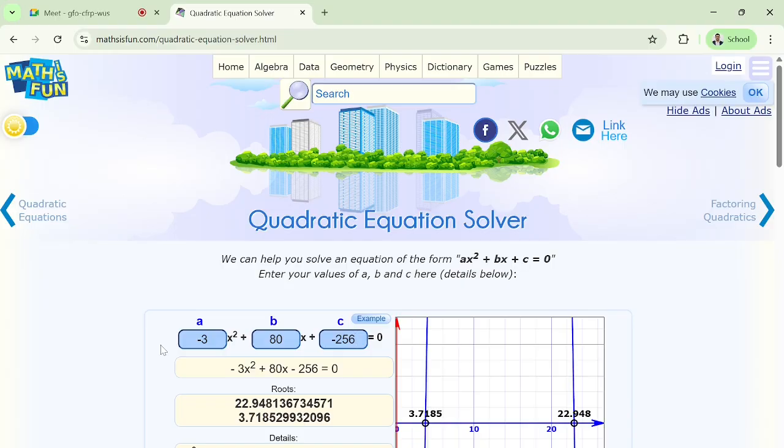Because dM by dz is nothing but V, already we equated that to 0. Again we are doing the same by equating the shear force to 0. Both are the same expression. So wherever my bending moment is maximum, there the shear force will become 0.